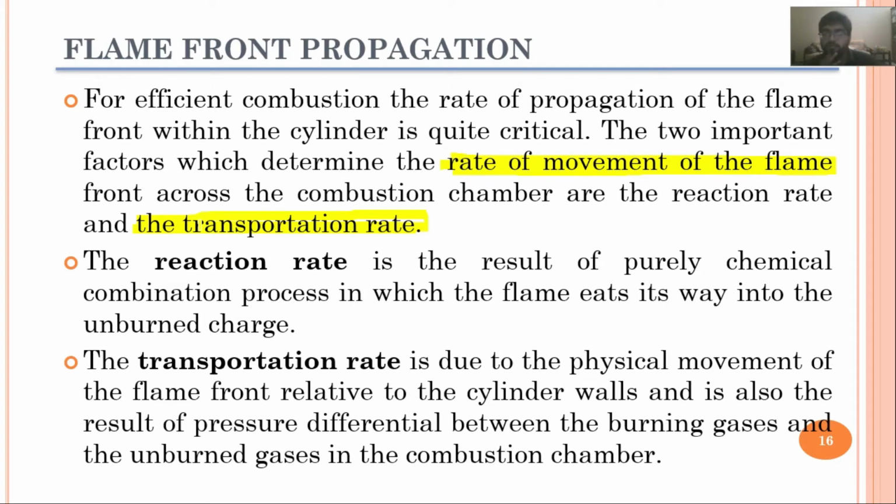combusting the unburned fuel particles as well. So this transportation rate is not a dominant factor in the flame front propagation, but the combustion rate, the rate of movement of the flame, plays a very vital role. So the reaction rate is the result of a purely chemical combination process in which the flame eats its way into the unburned charge,